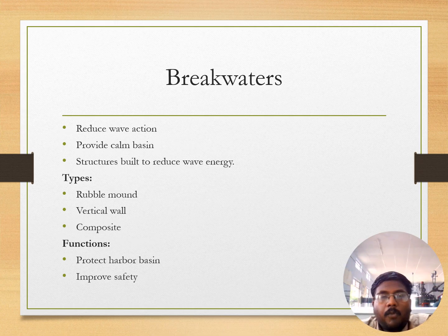Next we see about the breakwater. Breakwater is one of the coastal structures used to build around the coastal region. The main function of a breakwater is to reduce wave action, provide a calm basin, and reduce the wave energy.